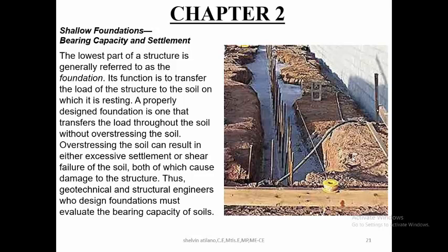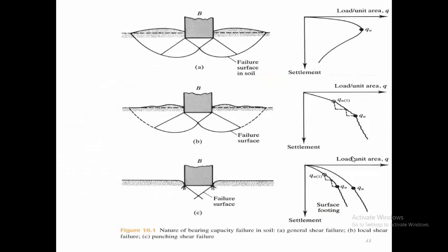A properly designed foundation is one that transfers the load throughout the soil without overstressing the soil. Overstressing the soil can result in either excessive settlement or shear failure of the soil, both of which cause damage to the structure. Thus, geotechnical and structural engineers who design foundations must evaluate the bearing capacity of soils.